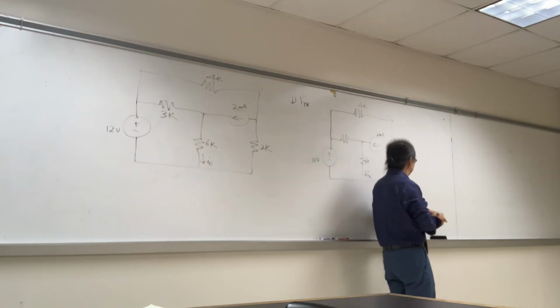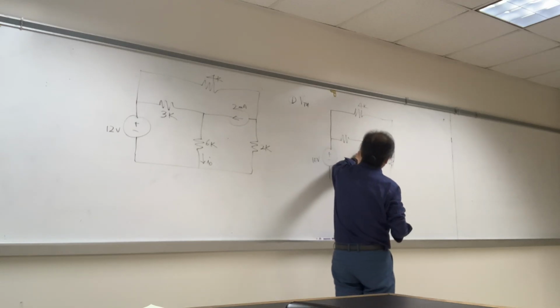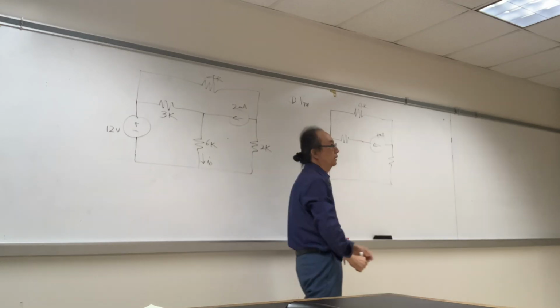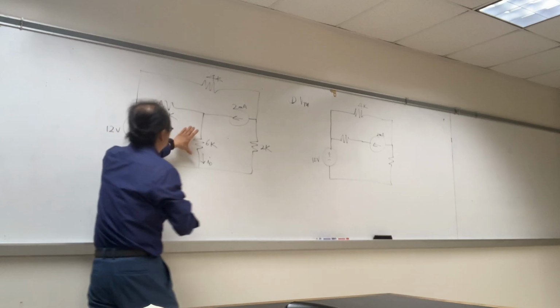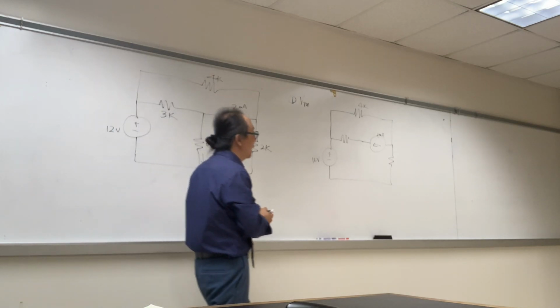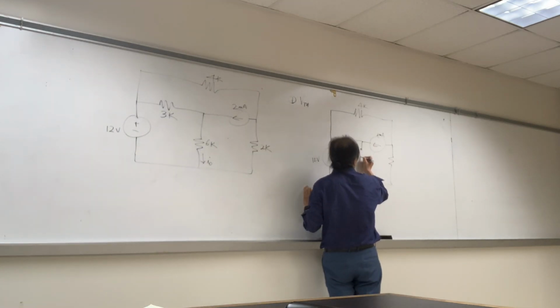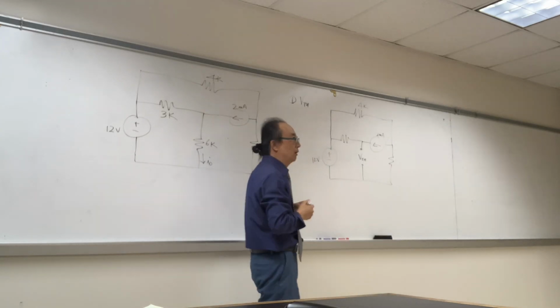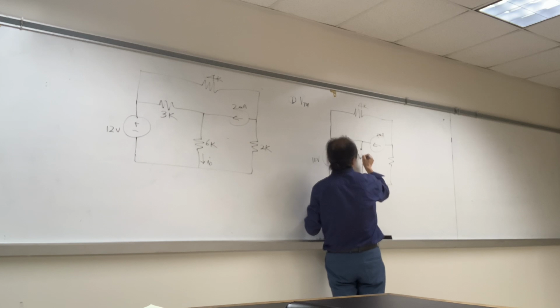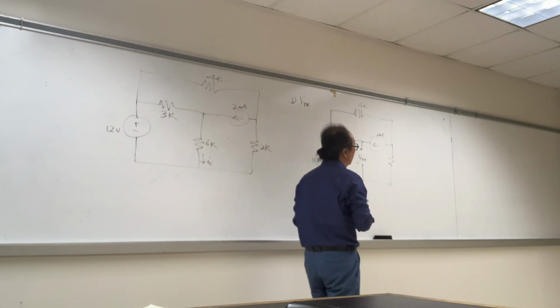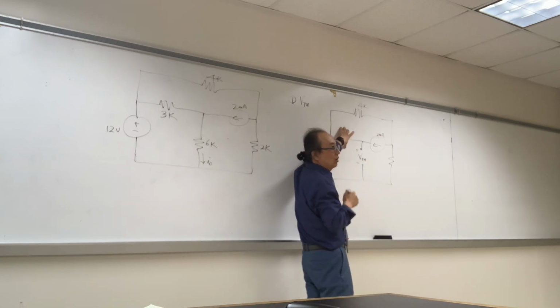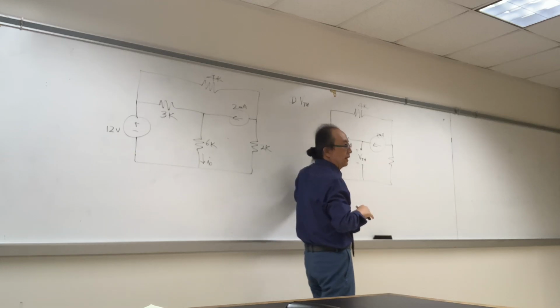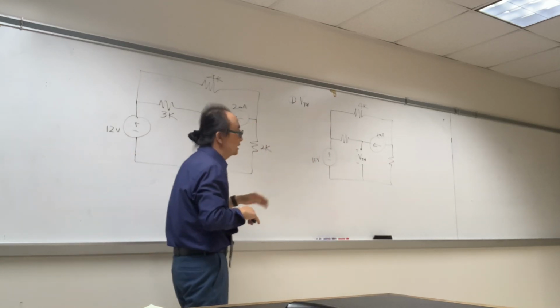The first thing you need to do is take out I sub naught. That's what we want, that's the load. Take the load out, and then we're going to replace that with VTH. When you write VTH at any given node, the top is always the positive and the bottom is the negative. If it's somewhere in the horizontal, then the left side is positive, the right side is negative.